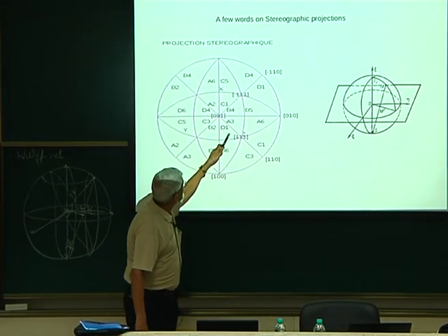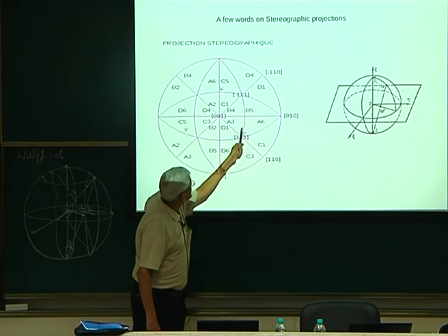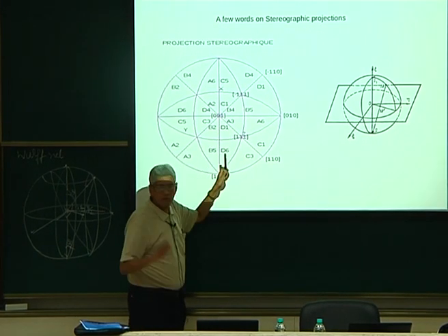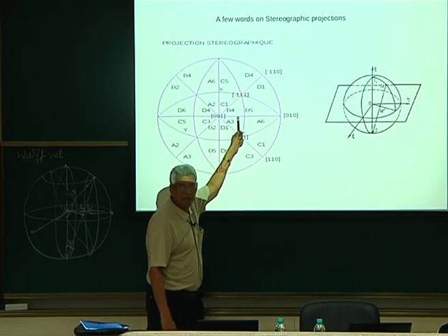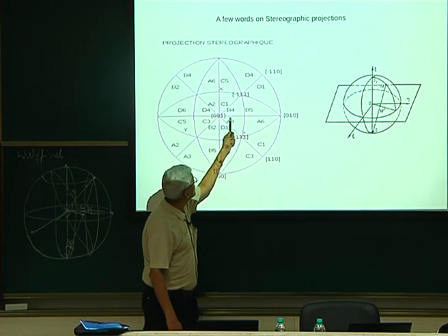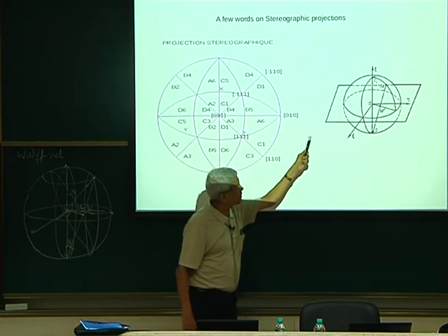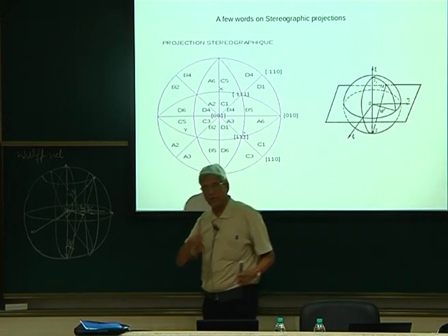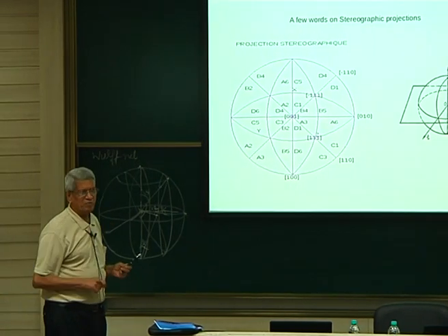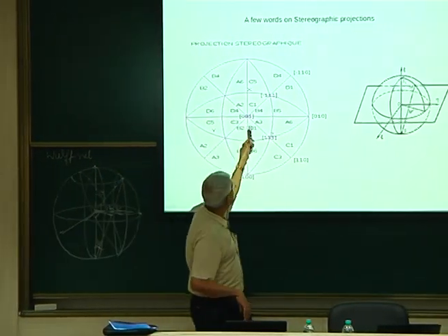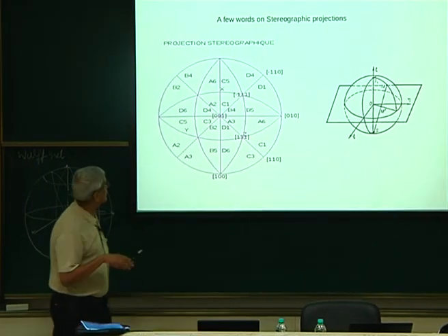Another thing, especially if you want to find out, let us take this stereographic triangle. So this is 0. By symmetry, if you look at FCC, okay, this is 1. Here this angle will be 45 degree, because of the distances: from here to here, linear distance, 45 degrees will come here, 90 degree will come here. That is because we write tan theta by 2. So the distances are not going to be linear, but the angle is what we are representing. So here the distances will be small, and as we go away the distance will become larger. Okay. Is this clear?